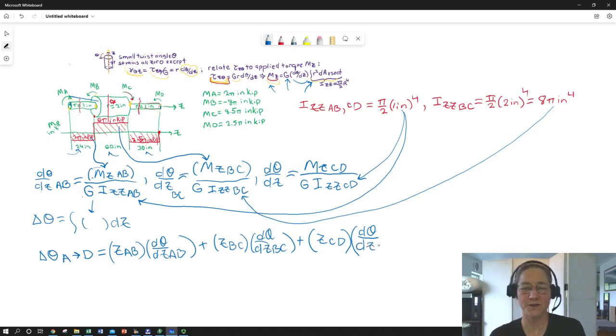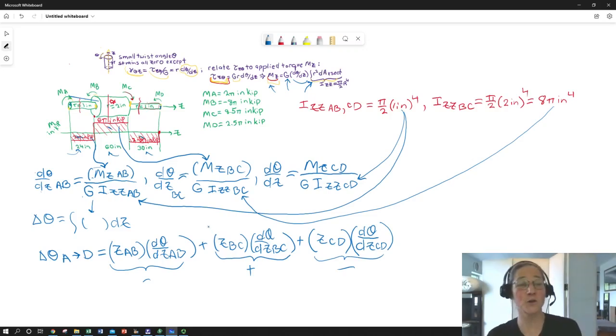So I'm just kind of talking through this and not doing a lot of calcs because I'm going to show you that on my SMath spreadsheet. Make it easy, so I can add up the total twist angle. This, in this case, is going to be positive, and this is negative, corresponding to the signs of my internal moment in those sections that's having to oppose that applied torque.